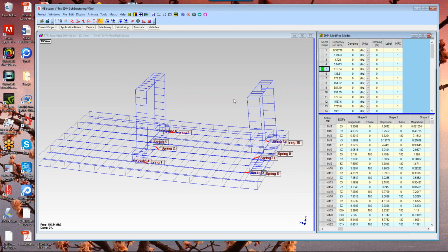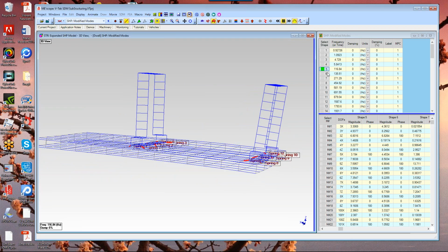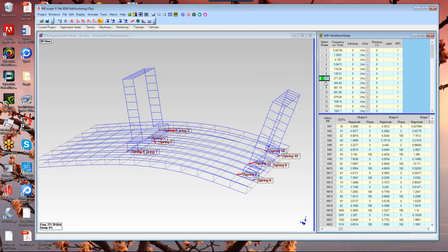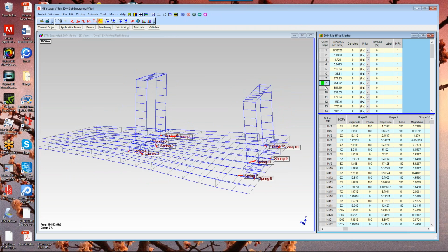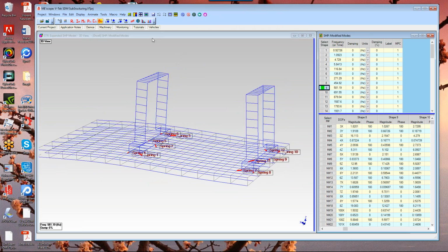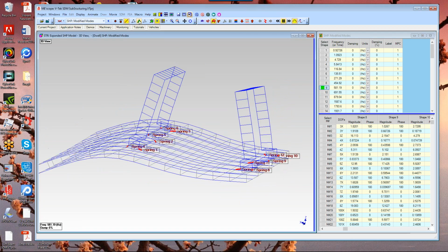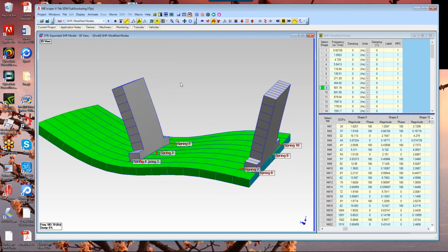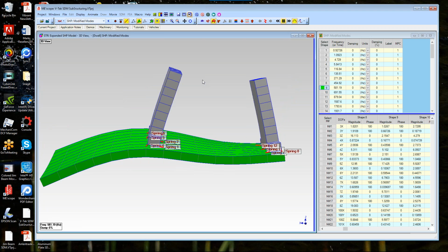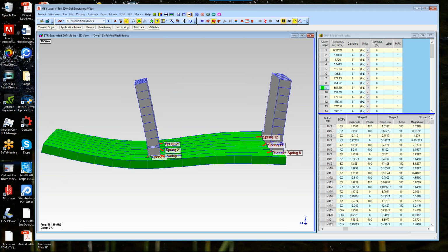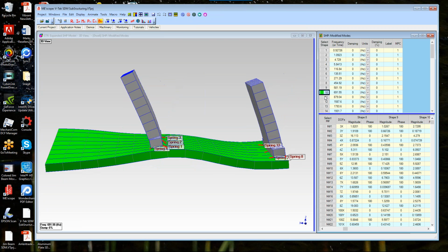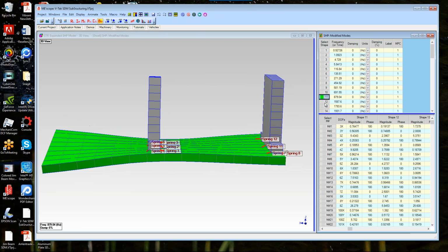First real flexure starts around 100 hertz, works its way up, and now at mode 7 we got first bending, first torsion, a second bending mode. I put the surfaces back on, it looks a little better. So, you know, we want to use this graphical capability in MEscope to look at resonances, and we can see clearly the different modes of this structure.